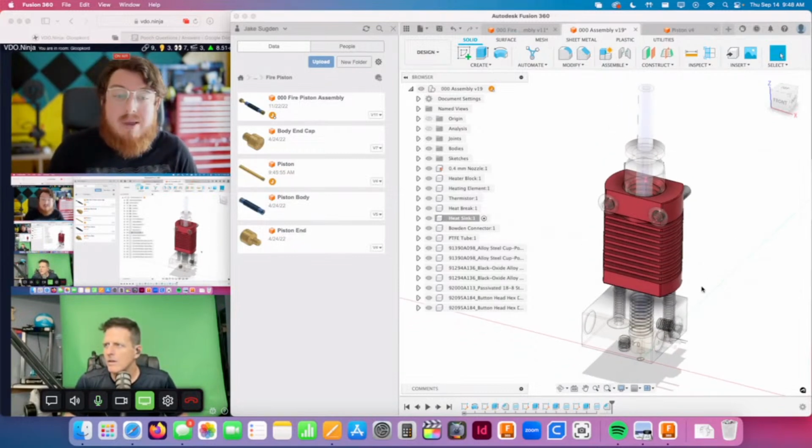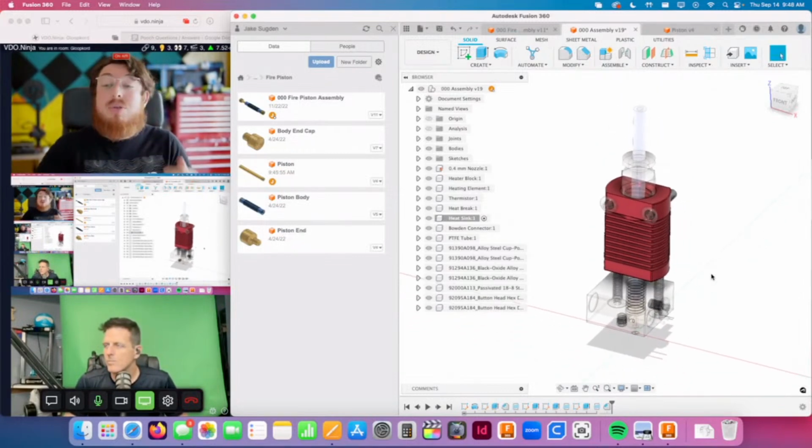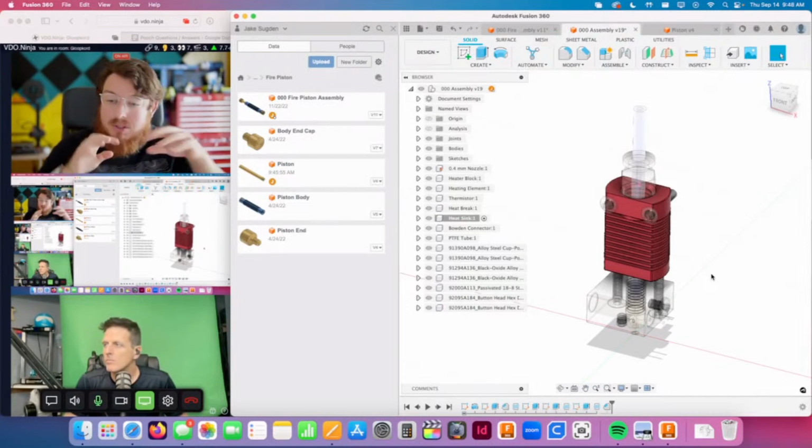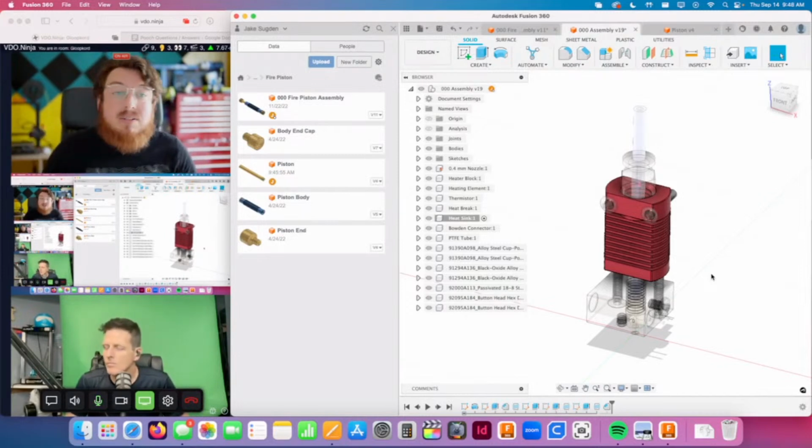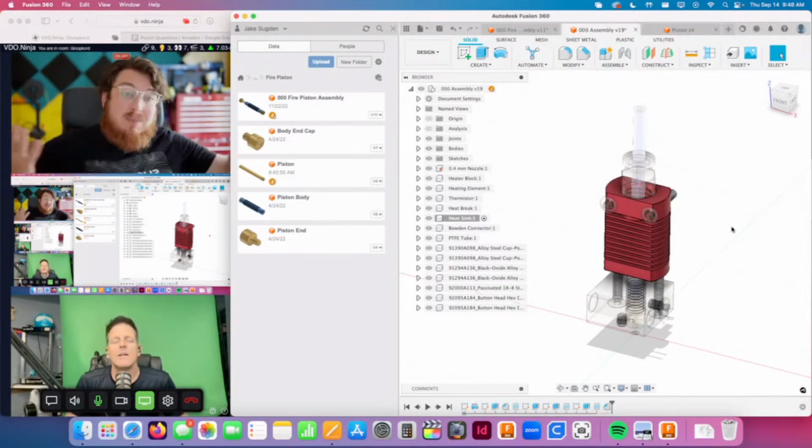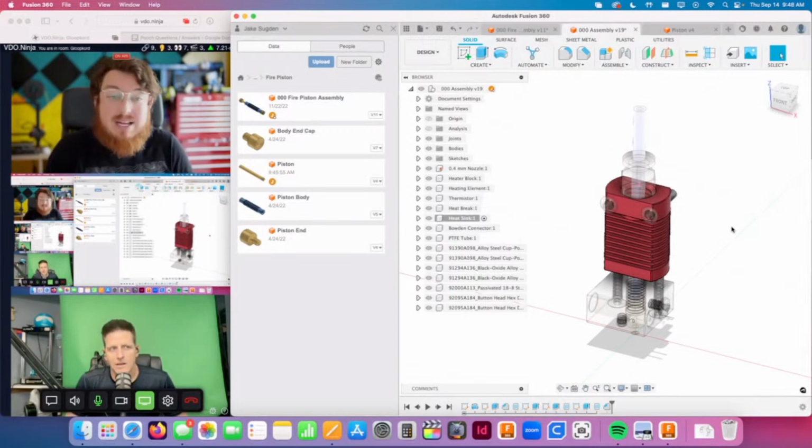So if you're making a product where things are going to be changing all the time, things may be changing because you 3D printed a prototype and this really needs to be altered and it's flowing into other components, then internal components are rad. But if you're working in a team where things need to be super organized, and the information needs to be spread out, or it's a little bit easier to understand, then you want to go for the external components.